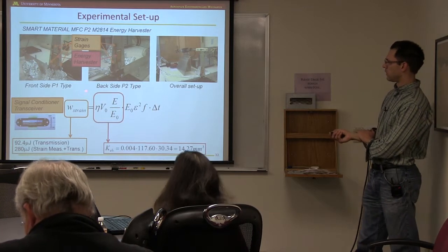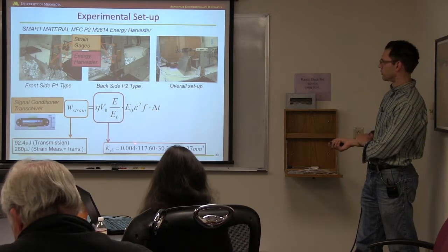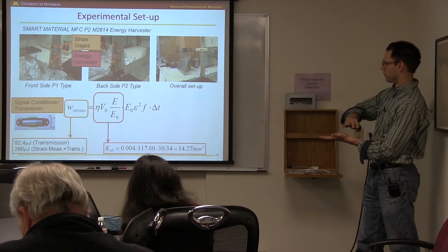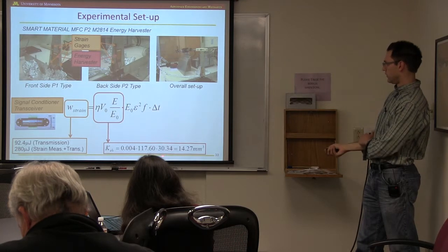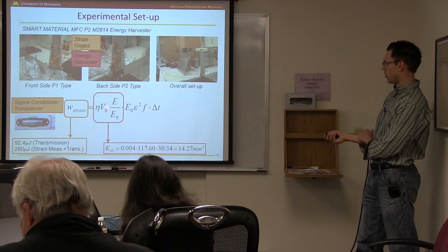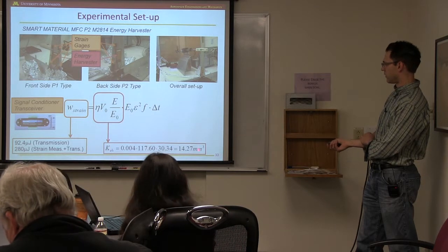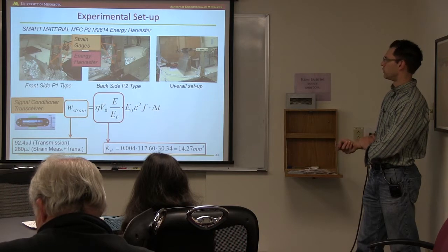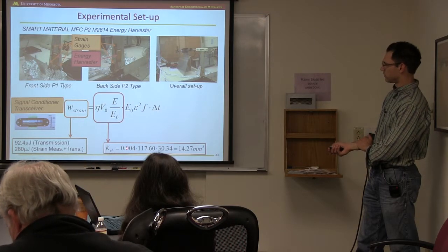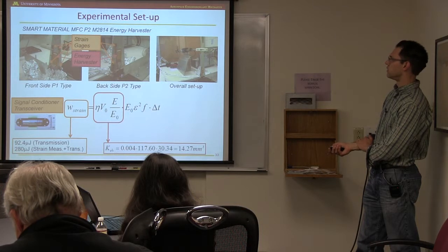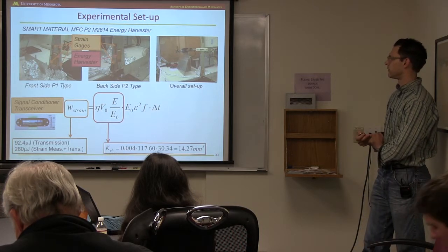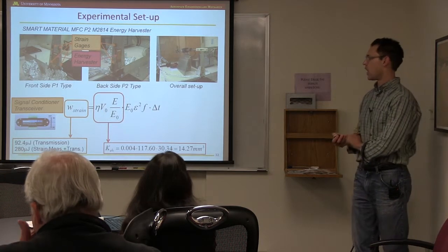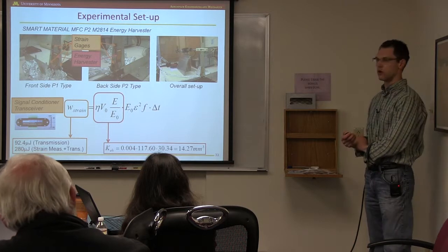One of the colleagues that I'm working with is designing nanotube harvesters. His efficiency is much higher at this point, but he can only do a certain number of layers of the nanotubes, and so he's got a much smaller volume. His harvesters have a number that's like a half millimeter cubed. So that's maybe at the more research level. The reason why this efficiency is so low is we're looking at something at a very low frequency. A turbine generally oscillates at a quarter hertz, and the efficiency of these piezoelectric harvesters is not very good at the sub-hertz level.